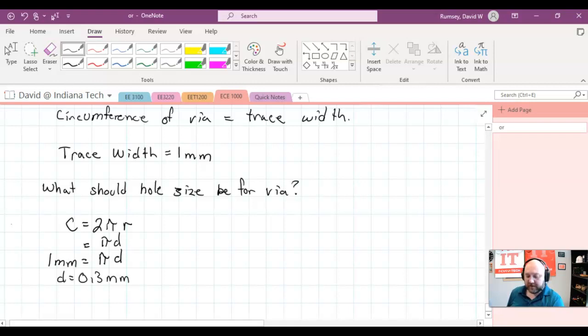But the via itself, being 0.3 millimeters, is actually a very small hole. We have drill bits that can drill 0.3 millimeters, but I don't let anybody drill that size of hole on our machine, because those drill bits spin at very high RPM and are very delicate, and you can break them very easily. We've tried, and I've gone through about 5 drill bits of 0.3 millimeters. The better way, if you're going that small, is to laser etch those holes.